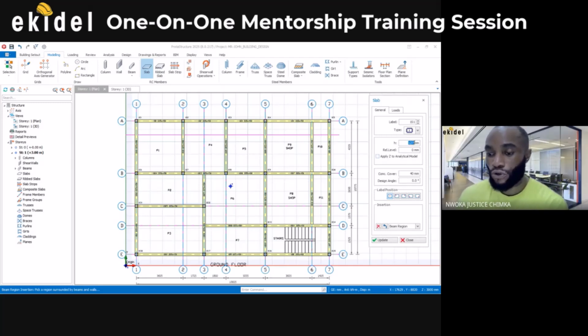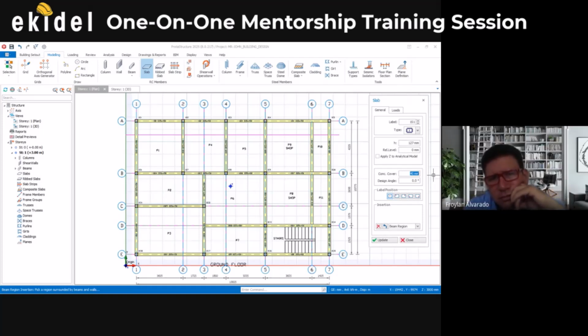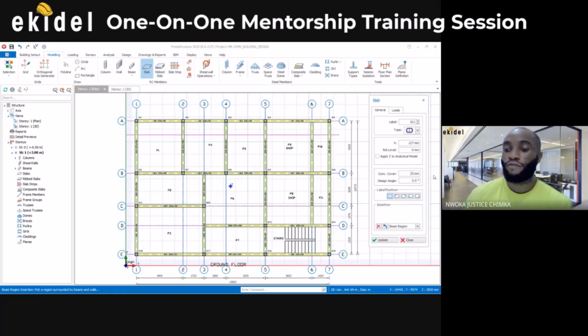So you put your slab depth and then the concrete cover for the slab. What do you use for cover? In my country we use 25. Yeah, same, 25. Okay, that's fine. Then you come here under loads. You can see loads here, you click on loads.